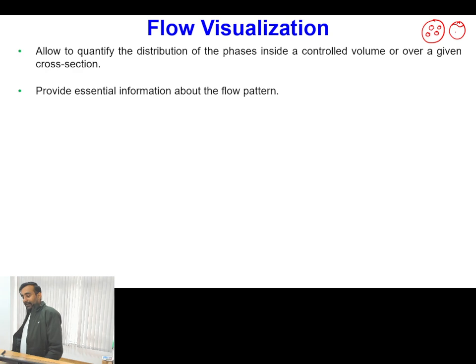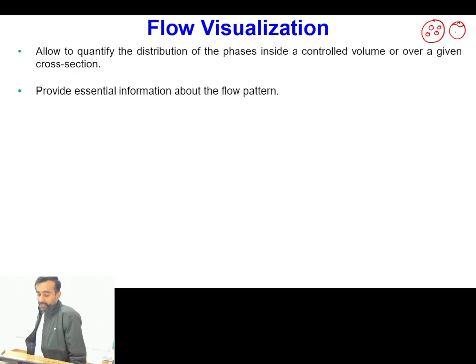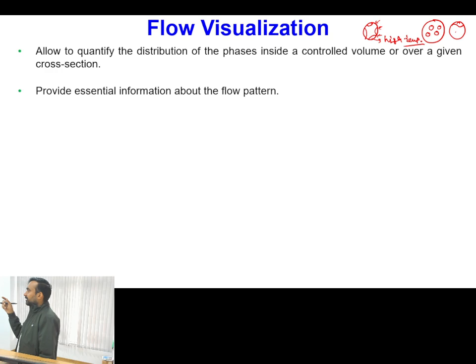And in certain heat transfer applications, knowing the flow pattern is also very important. You can take one example. Say you have a heated rod, and in this heated rod you have multi-phase flow. Then the portion of the heated rod which is contacted by the gas bubbles will have extremely high temperatures. Why high temperatures? Because if you subject this heated rod to a constant heat flux condition, then from outside you are adding the heat flux at a certain rate.